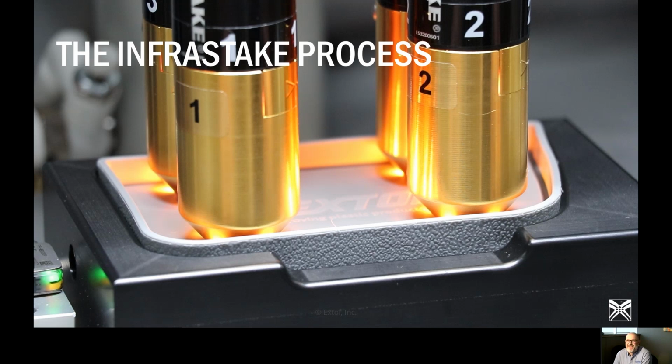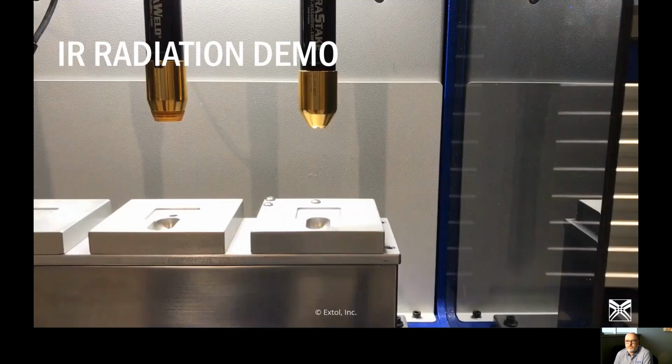Yeah, thank you. So you can see that that boss was a 1/4-inch boss, polypropylene, and we took 9 seconds to stake that. The lamps were on for 5 seconds. Punch extended for 4 seconds. Again, we don't just hit it with a punch and retract. We hold everything till it's resolidified. That's why there is a 4-second punch time there. So cycle time on that was 9 seconds.